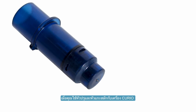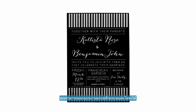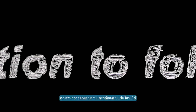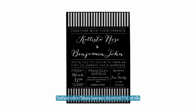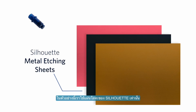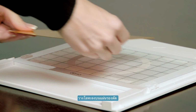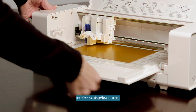When using Silhouette's stippling and etching tool with your Silhouette Curio, you can etch designs onto select metal surfaces. In this example, we will use Silhouette brand metal etching sheets. Place the stippling and etching tool into the Curio's left tool holder. Place the metal sheet onto the cutting mat, then load the base into the Curio.